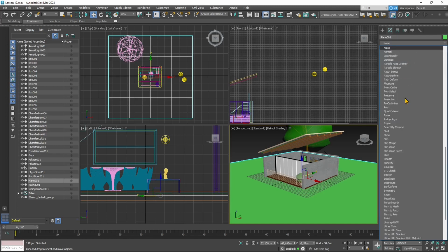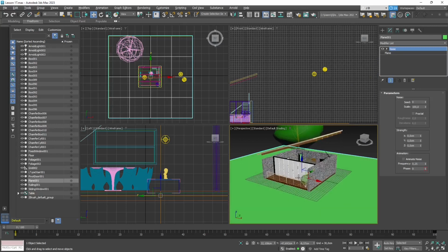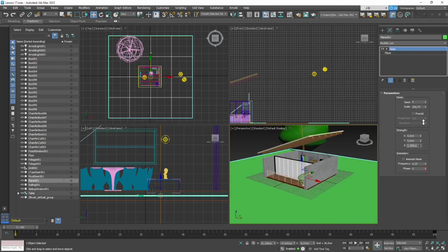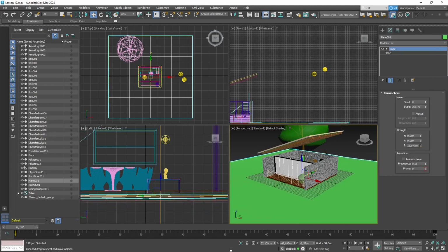But one thing I can actually do real quick to the modifier is I can apply a noise. Now we saw that the noise is something that we want to get rid of when we are talking about rendering, but this is also an effect which is going to create not a uniform look to the object where we apply it. So if we are creating a terrain, something that is supposed not to be so flat, we can directly apply a noise, and that's going to be a real effect in this case. So this is not a fake bump effect, this is an actual noise.